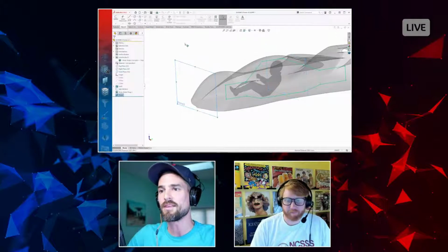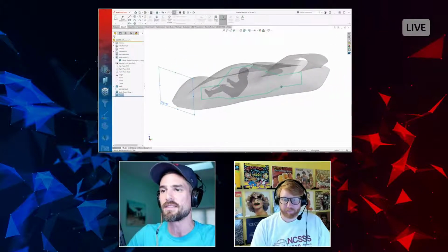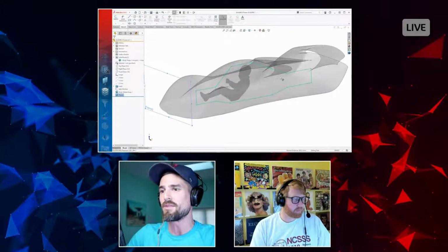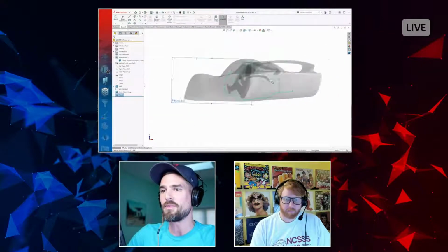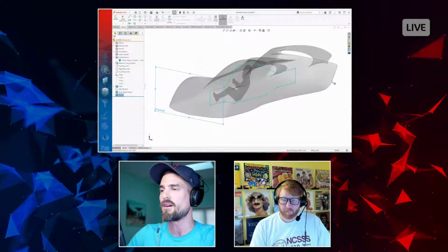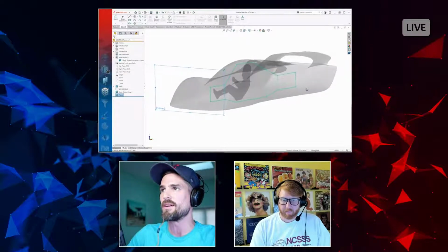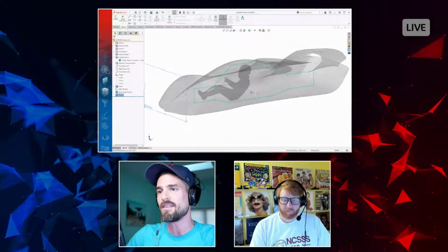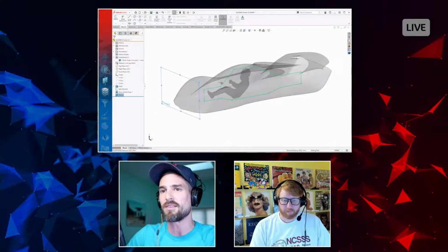Okay, nice. So the reason I'm creating this plane is because what we're going to be creating is a 3D sketch. And let's imagine that we had a completed 3D sketch of the frame. How would we know if there was any interference between a 3D sketch and Jason's awesome model that we're seeing here, transparent right now? We really wouldn't, right? Because the visibility of a sketch entity is the exact same whether it's covered by a transparent model or not. So it's not the most ideal situation.